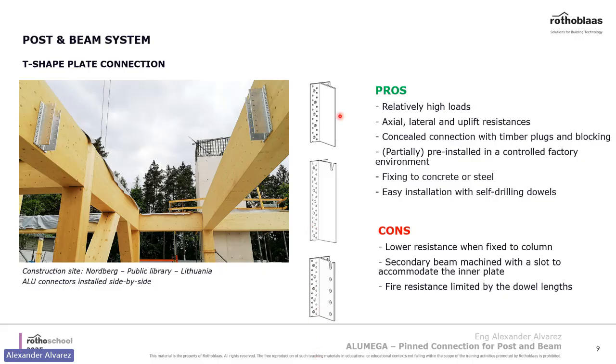You can see these knife plates get bigger. This one is about 4 inches, and it can go all the way up to 20 inches. So they can get pretty long, pretty big. But you're limited by the section of the beam. Maybe the beam is only about 20 inches, and we have a 20-inch knife plate, but it doesn't give you the capacity you're looking for. So that's something to keep in mind, and also the fire resistance.